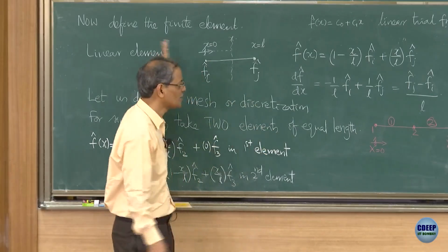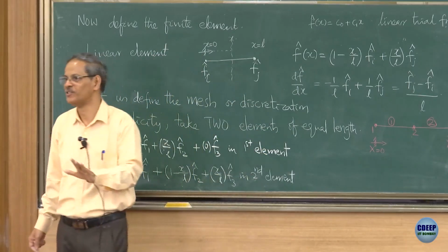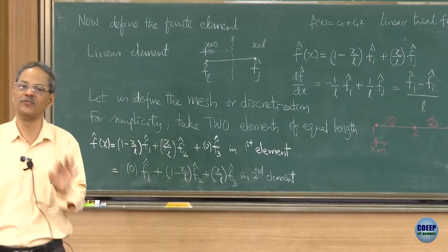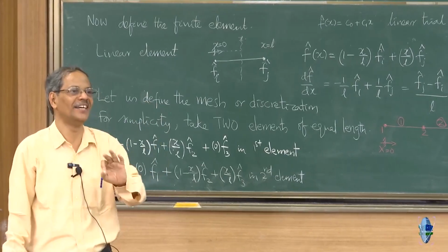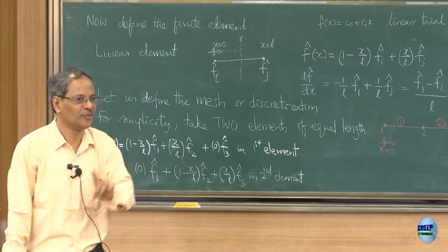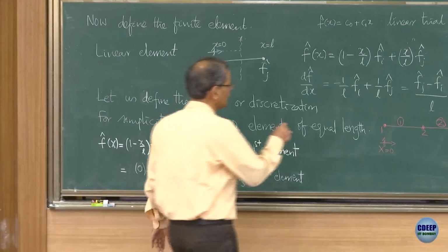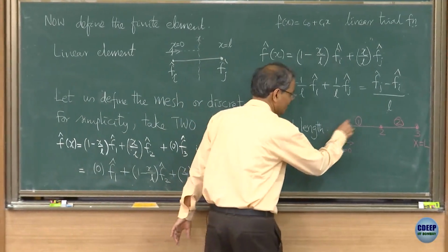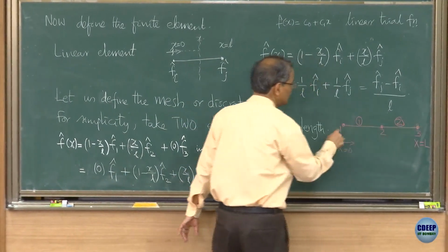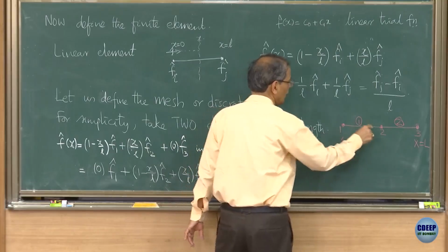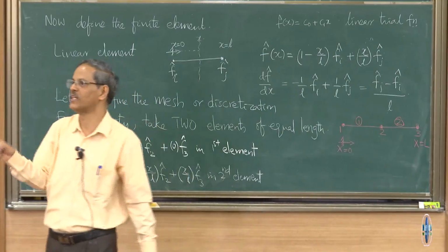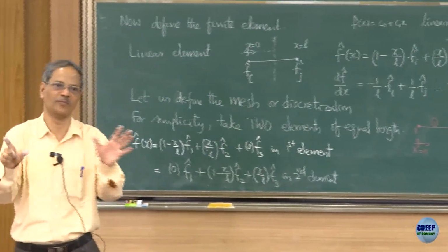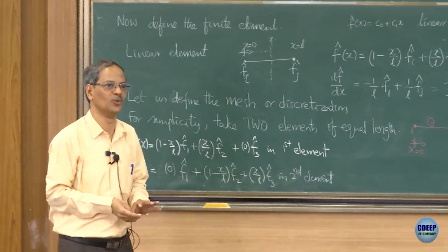This whole process we are doing through finite elements is to simply convert that one differential equation into many algebraic equations. Each algebraic equation is centered around that particular node. So you will have 3 equations in f1 hat, f2 hat, f3 hat. 3 equations, 3 unknowns, we can solve. So that's how I am going to propose the whole formulation.